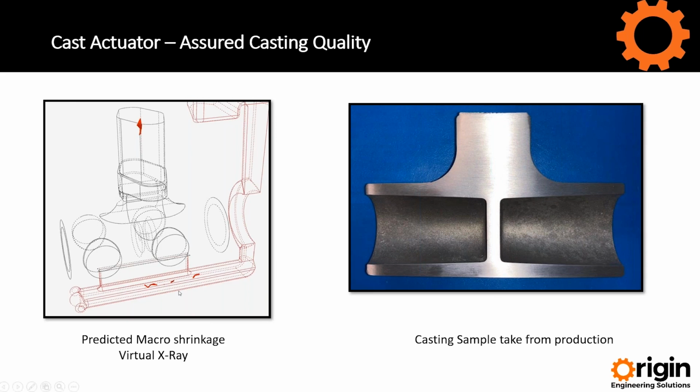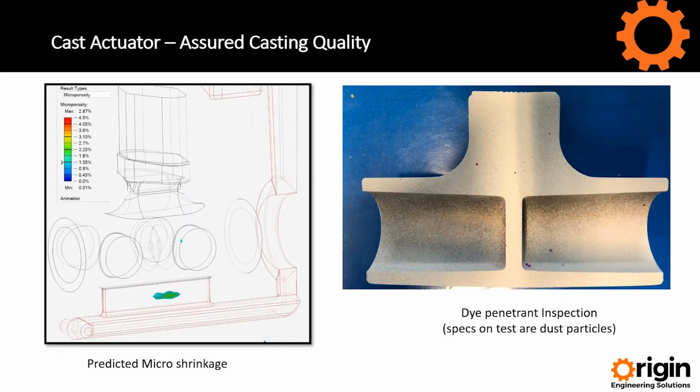With aluminium, not only macro, but I could say that with a lot of cast materials, we need to look at micro shrinkage. I have to go on my soapbox here. Please do not use the word porosity, because porosity means a multitude of sins.